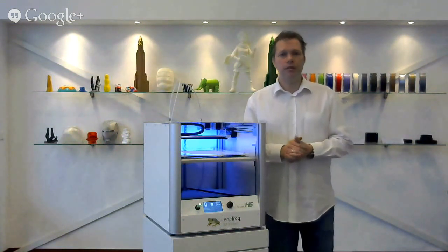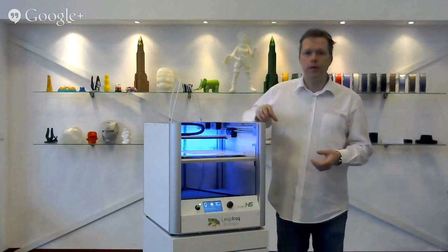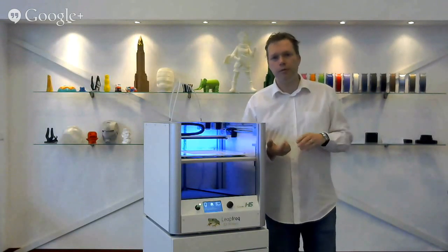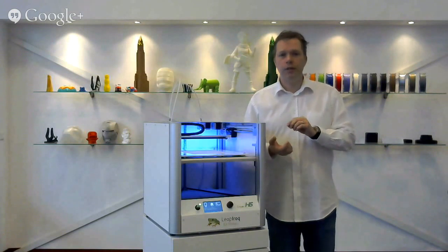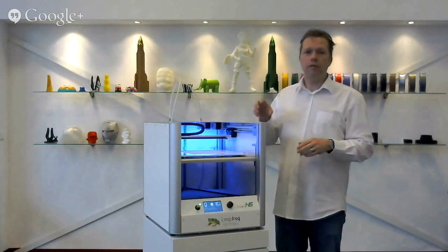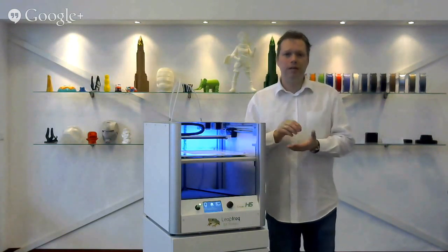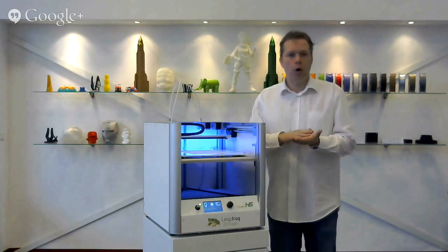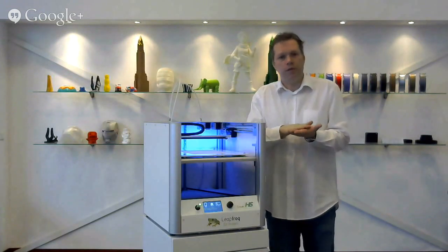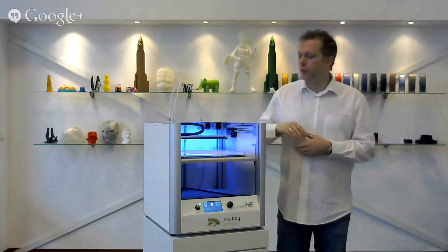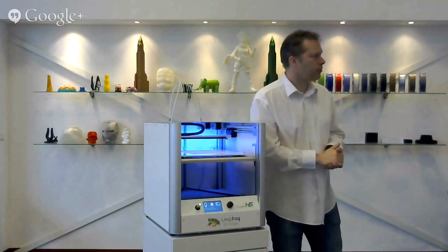The most common disadvantage is when you pull off your print, on the bottom side of your print, you can still see the tape, because you will pull off a piece of tape and it will be embedded inside your print. So you will always have that little blue fluffy stuff on the bottom. You don't want that. So that's why we use the print sticker.